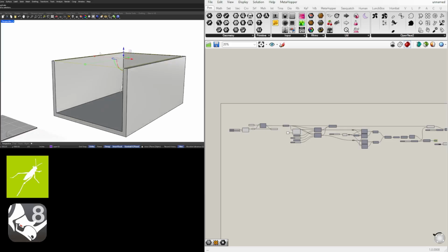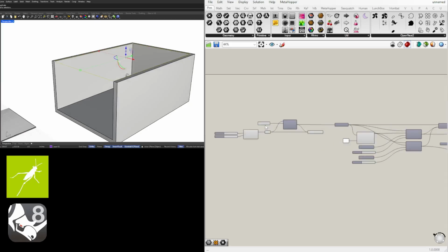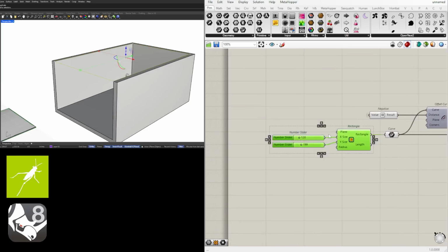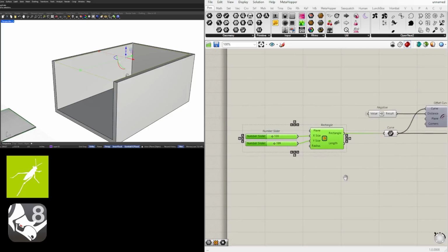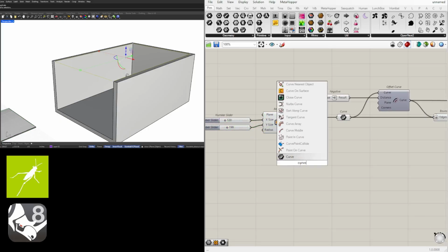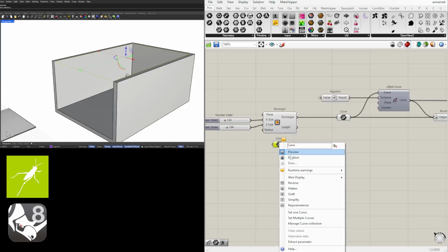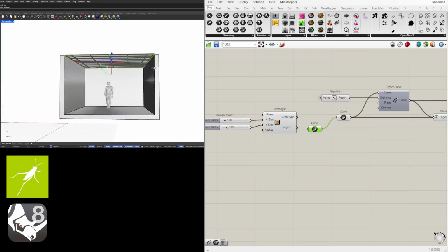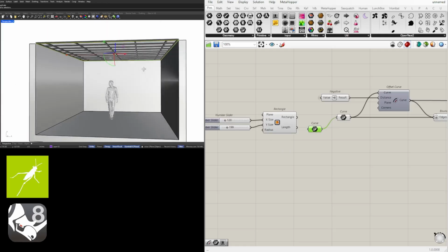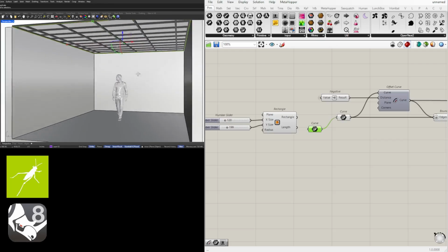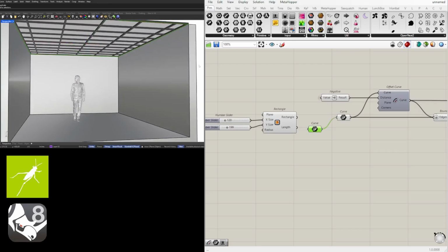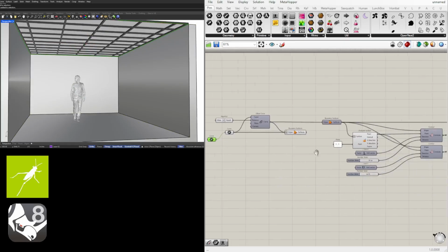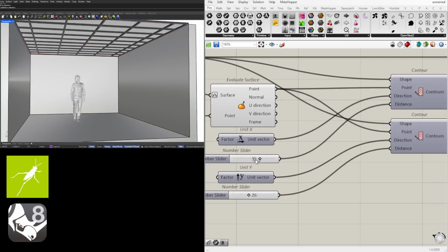And then use this curve that we just created as the curve input. So this is a parametric rectangle. If I use a curve component and I set one curve, the one that is here in Rhino, and I override it, notice that it creates it here. Now let's move around some of the components and you'll see what we can do here. So changing the size.